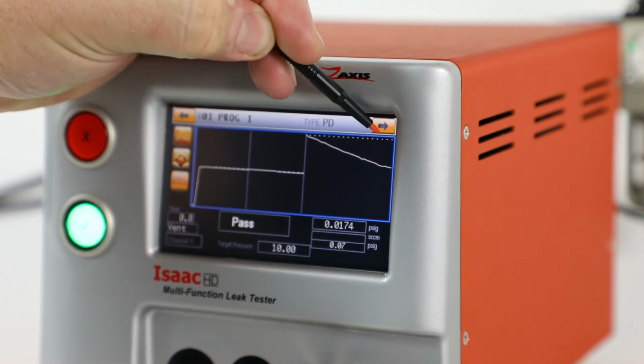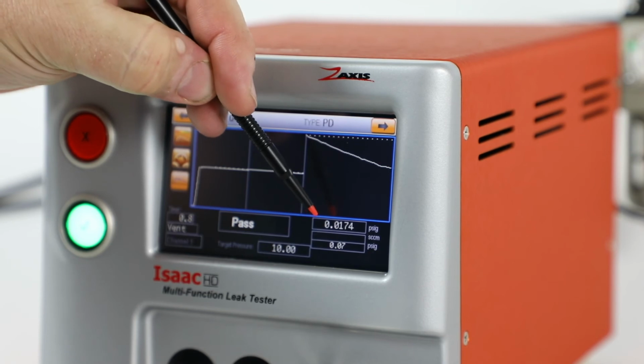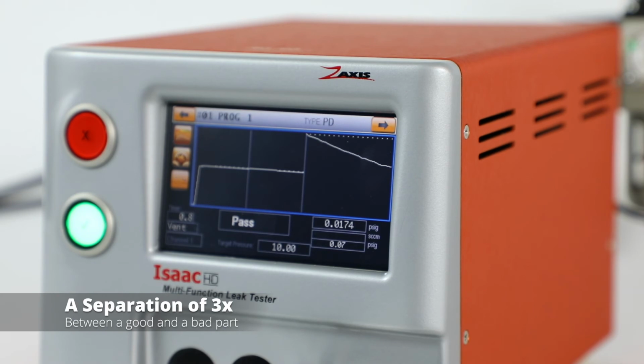Really what we're looking for is the difference between a good part decay and a bad part decay. Is there enough separation between these two numbers? If you recall, the first test was 0.0001. So we have about 170 times difference between those two values. We typically say that a good test should have a separation of 3 times. So a good part and a bad part should be 3 times each other, no matter what the numbers are.